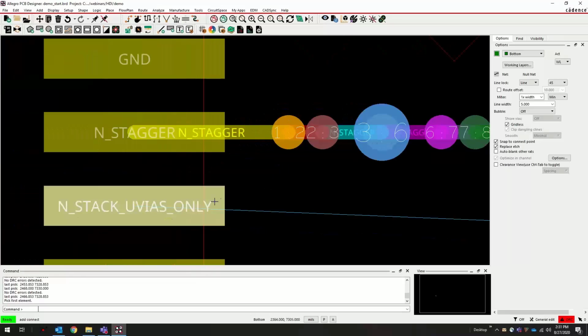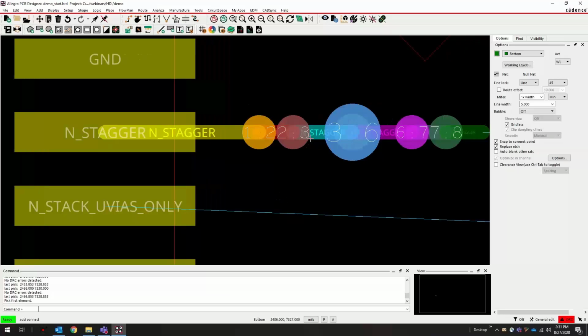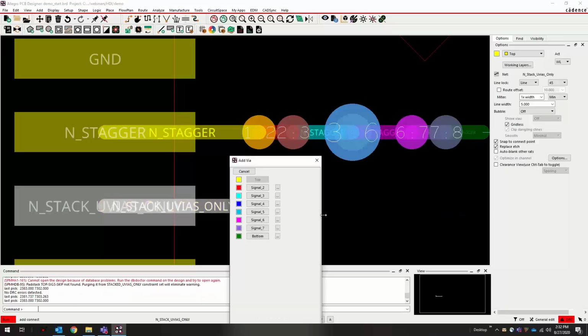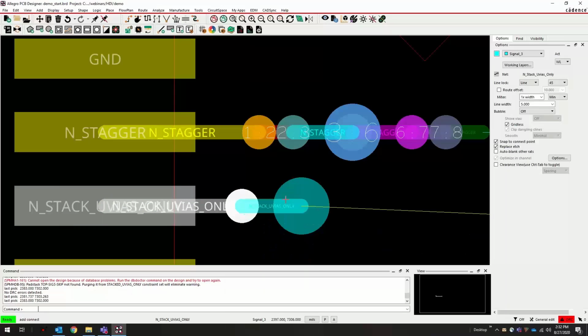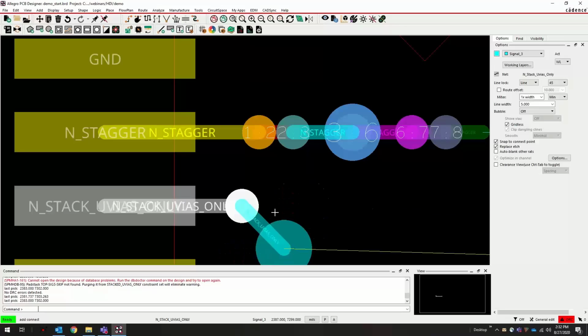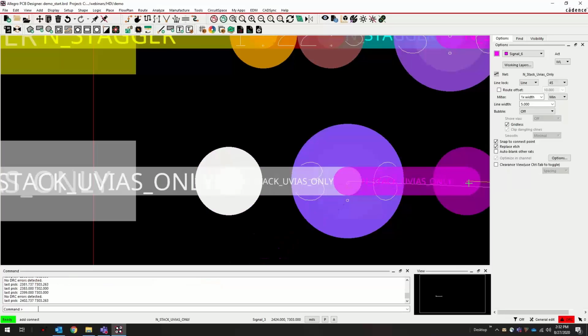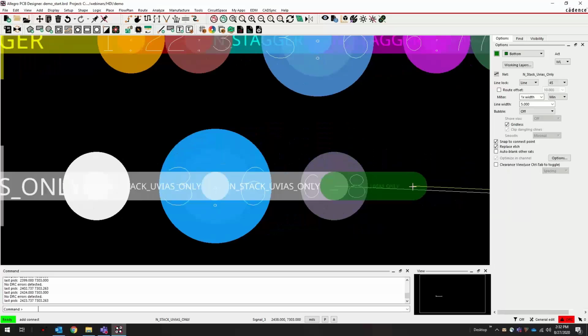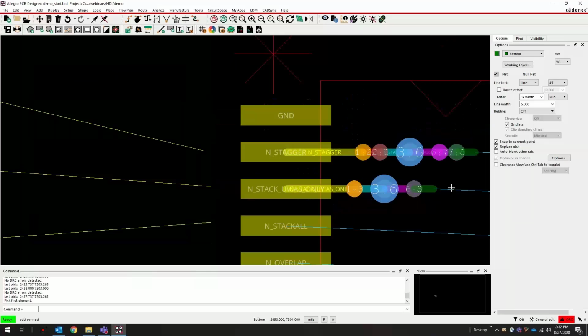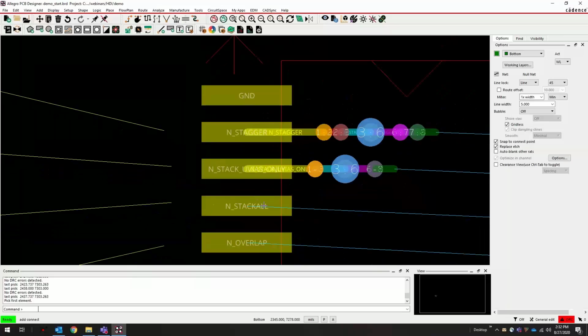This next one is going to be stacked microvias. So the two microvias will be stacked here, they'll be stacked here, and then they'll be staggered from the core via. So once again, I'm going to try to get down to the bottom layer. And now you can see my two microvias got stacked. So now put the core via down and then the next set of stacked microvias, and then I'm down to the bottom. So you can see the difference in the two of how they look here.